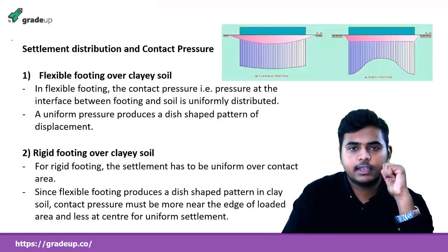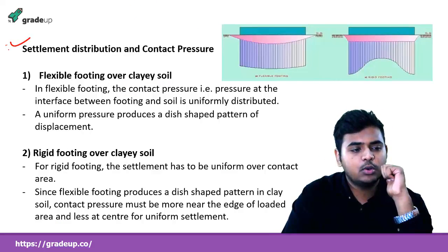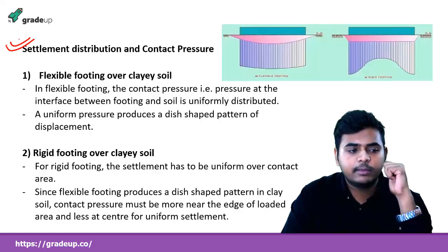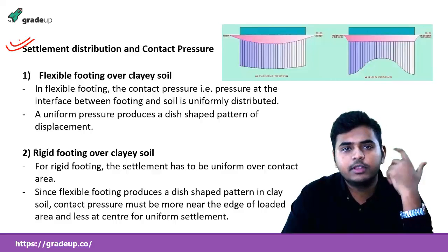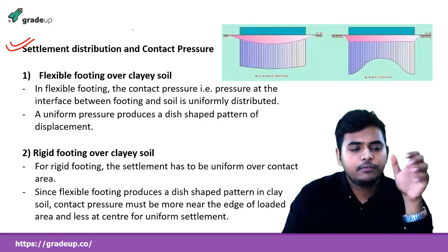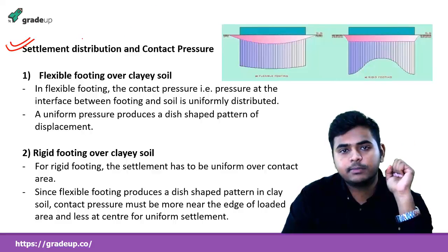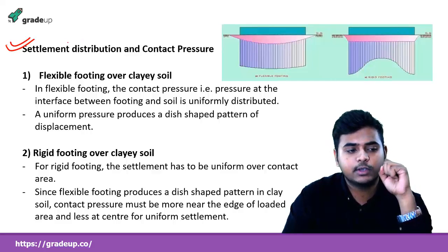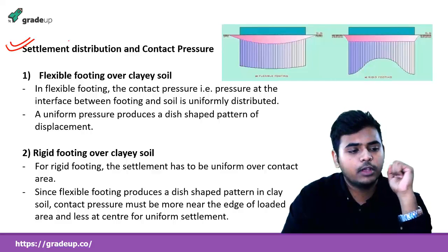Now coming to the next concept, there is settlement distribution and contact pressure. This is generally asked in the GATE and ESE exams continuously. They go on asking every 2 or 3 years. Now what is this concept? You have to actually find that there are 4 cases in this: flexible foundation and rigid foundation, both for clayey and sandy soil. Now let's take it one by one.